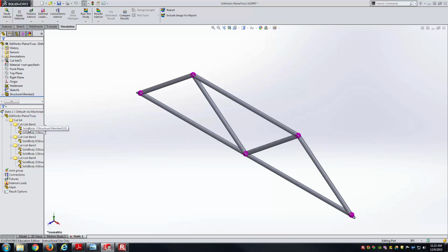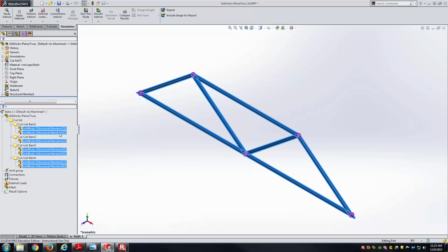That kind of I-beam shape actually shows that they are beam elements. What I'm going to do is just hold control down and select all of the bodies. If I pull out, you can see them a little bit better. I'll right click and go apply/edit material. Here I didn't have to hold control. I could have clicked on the top node and said apply material to all bodies. Either way would have got me there.